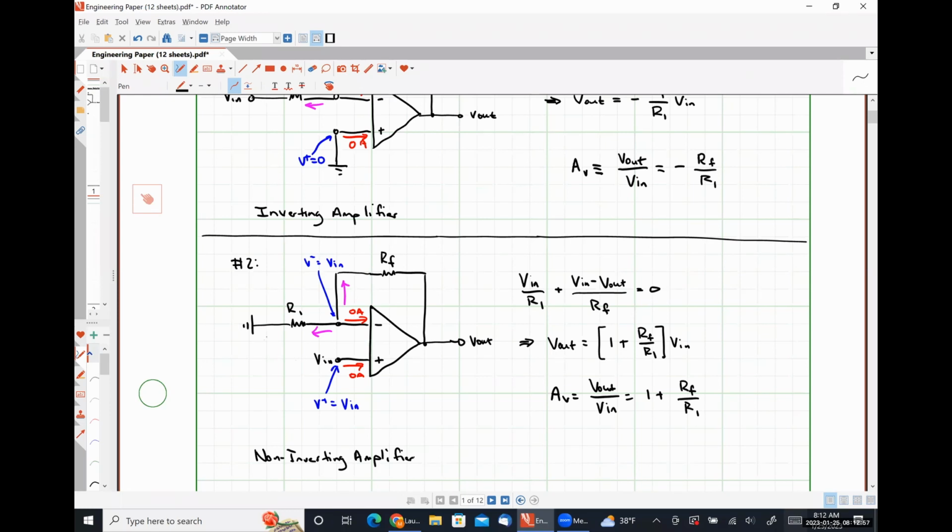Okay. So this non-inverting amplifier can only amplify signals, right? So the smallest possible output signal we could get is just the input signal itself, because we're always going to have 1 plus the ratio of resistances. So if R1 is much larger than RF, we get what's called a buffer amplifier. Whatever you put in is equal to what you get out. You might be asking yourself, why would you ever want to have an amplifier with a gain of 1?